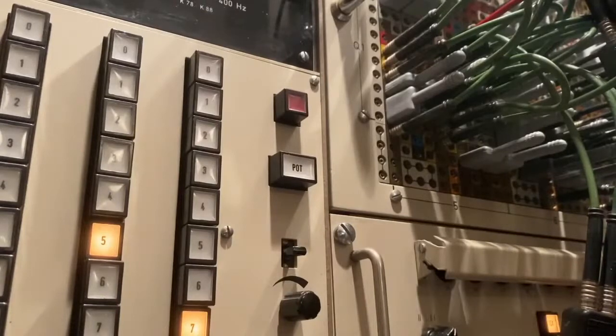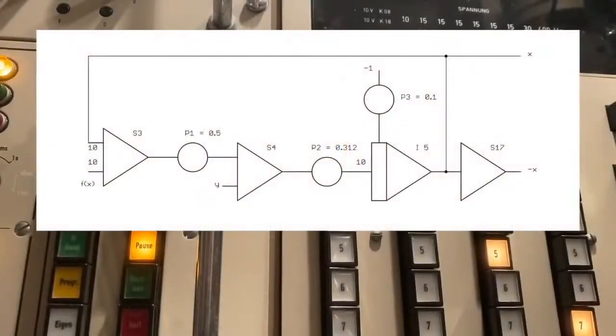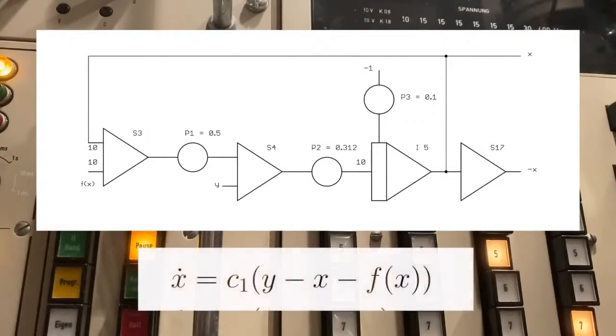But when we assume that the scaling operation has been completed, we can now start to set up an analog computer program. And programming an analog computer means, as you already know, to interconnect the various computing elements so that they build an electronic model of the underlying mathematical problem. The figure shown here, which is figure 1 of the application note, shows the subcircuit which represents the first equation of the original problem in its scaled form, which describes how the variable x changes with time.